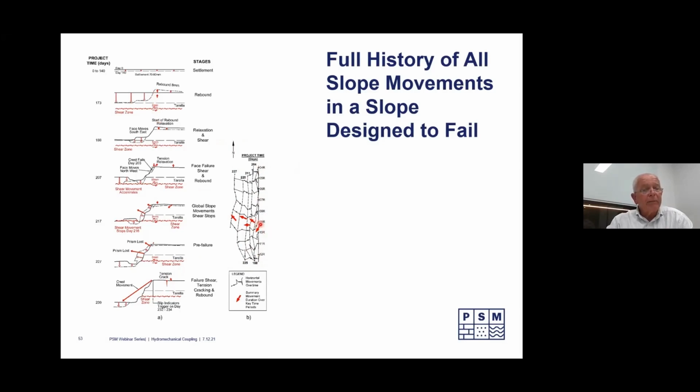As it was excavated, surprisingly, the slope wanted to move in this direction. Then over time, it started moving in that direction. And then finally over here. And this direction was related to those open joints I talked about. So geological structure, in situ stress, the different geological units, the role of structure, continuous structure, all played a role in what is a complex system.